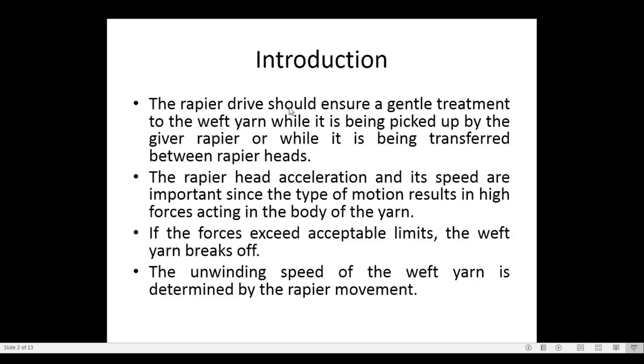So this Rapier drive should ensure a gentle treatment to the weft yarn while it is being picked up by the giver Rapier or while it is being transferred between Rapier heads. So gentle movement is required here. This is the main function of the drive. If the drive is not proper, the weft breakages increase.